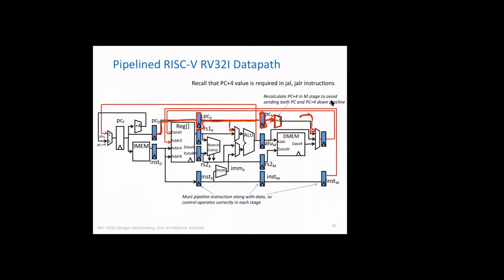Okay. Any other thing you notice? We do pipeline because a number of instructions have got to be in flight. So different parts of the same pipeline should be used by different instructions. Okay, if you don't put registers, then the signal will flow. As soon as you access the second instruction, all this signal flow that we have seen in single cycle design will happen and cause problems.